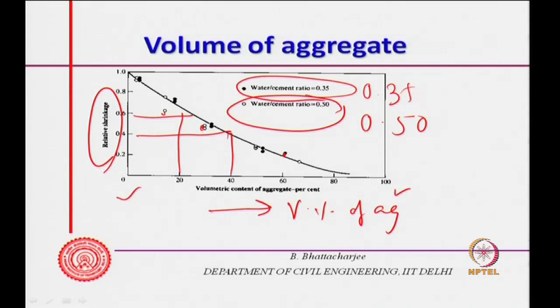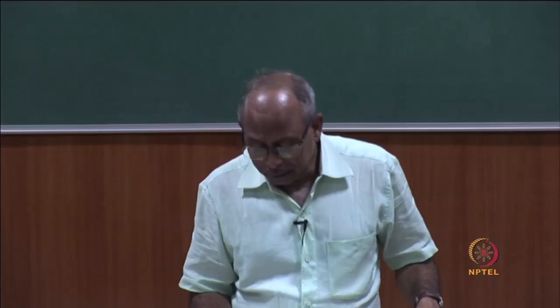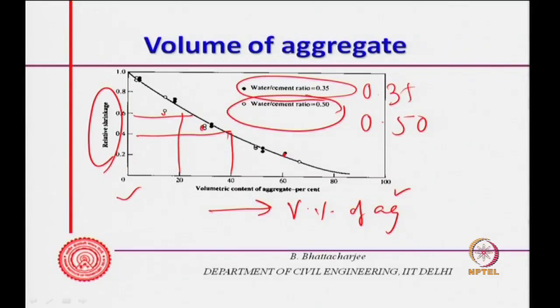More volume means less shrinkage. Of course, we are talking here about the shrinkage in the system itself. There is a case where you have a very low volume of aggregate, where the shrinkage in the overall system could be lower, or shrinkage cracking could be lower. We will talk about that sometime later on.